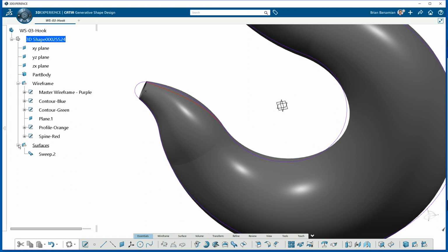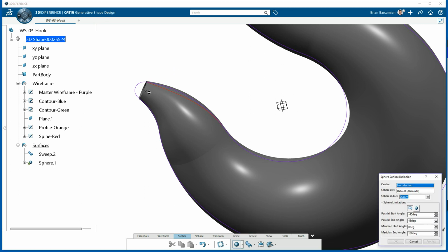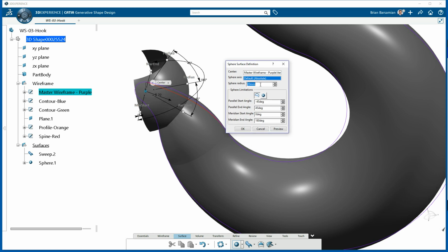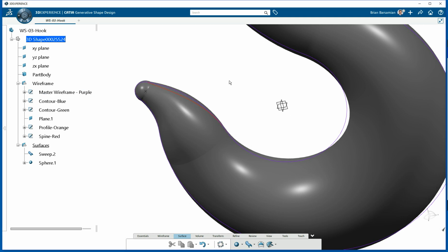Okay. And that point is going to be used to make a sphere. So I'm going to come down here and go to my surfacing commands, and let's see here, where we go. There we go. There's my sphere, and I'm going to pick my point, and the radius is going to be 5. We're going to make a complete sphere of a radius 5. Okay, great.